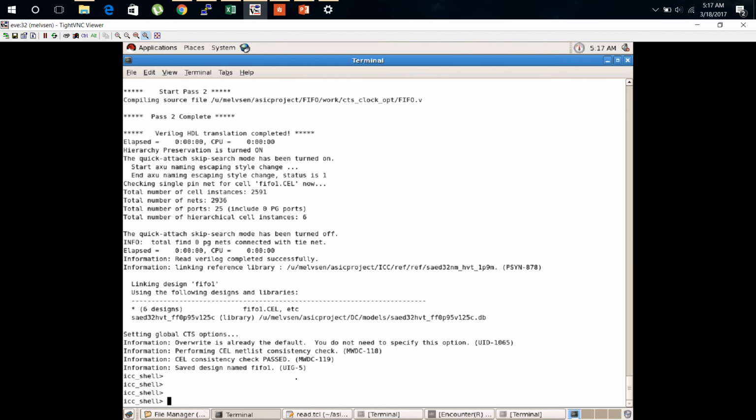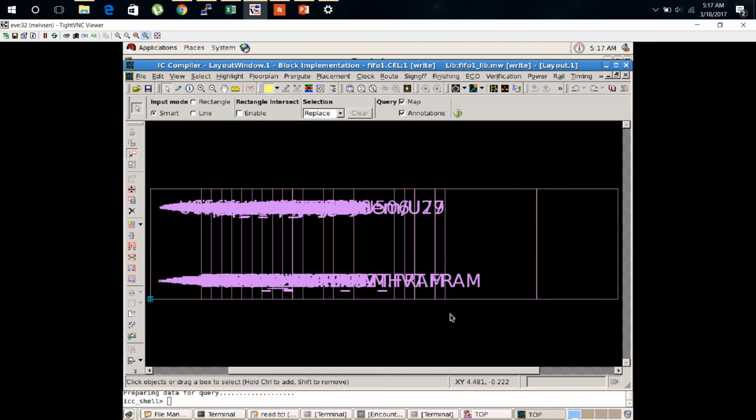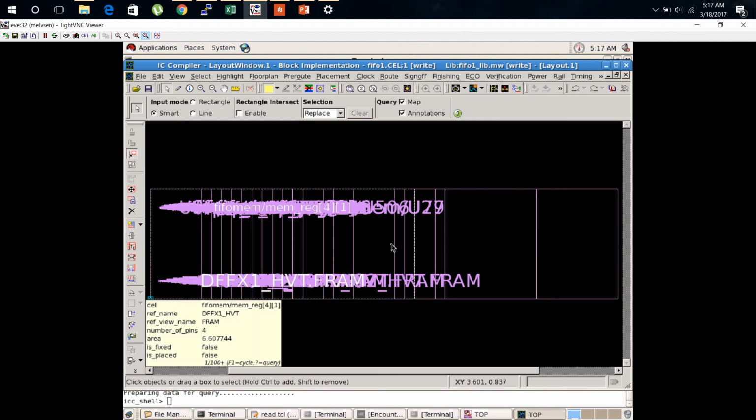So we can open this GUI for this process. This is the state of our ICC design process, where we have almost all the cells that we need. It has mapped all, it has understood the netlist that DC gave, and it has collected all the cells that we need to successfully arrange and optimize into our ASIC chip.